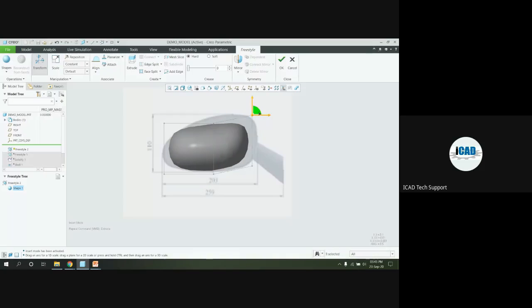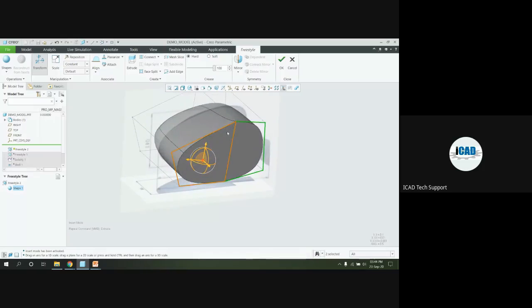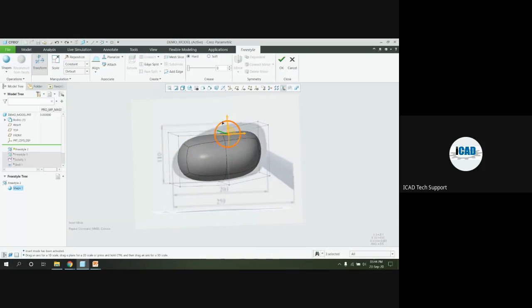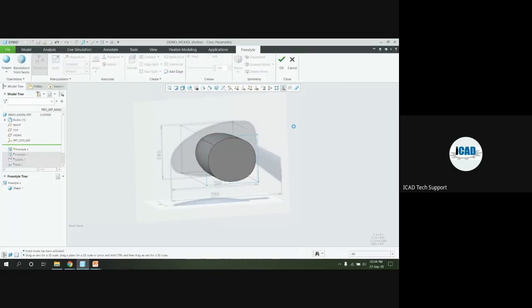So you can see, quickly you can just drag and drop those node points or those areas. So how we can create the sharp surfaces, I will show. If I select those front two surfaces, here the hardness crease option is available. In the hard and soft, you can just set the values for it. Now you can see, if for the front surface I want the hard as a planar surface, I am just selecting it as planar and clicking on the front plane.